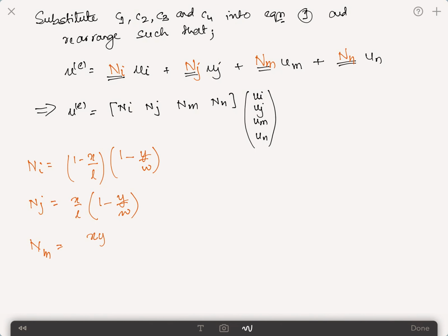So these are the different shape functions that we will arrive at in the standard coordinate system that we are already used to. So up until this point, I want to use the standard formulation for elements, just using x, y as the coordinate system. That means we are moving from limits 0 to L for direction x and 0 to W for direction y.